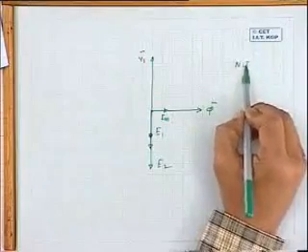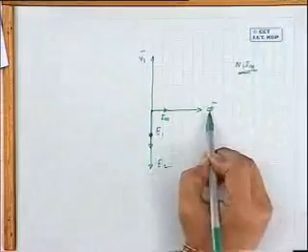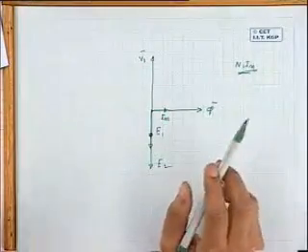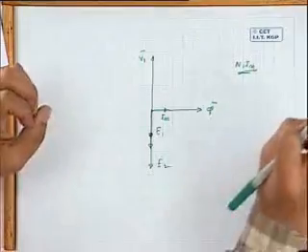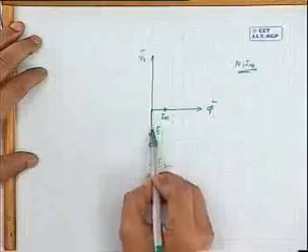Under no load condition, what was the MMF acting in the circuit? N1 into Im, and it established this flux phi. What I am trying to tell is, if you load the transformer, let the secondary carry current, let the primary carry extra current or not, I do not know, some currents let it carry. But the net MMF acting in the circuit should be how much?